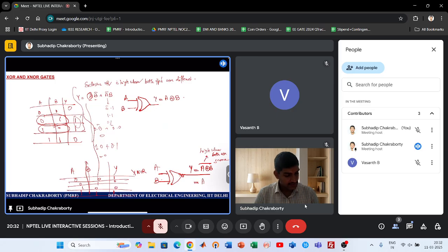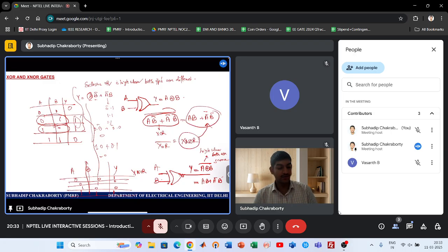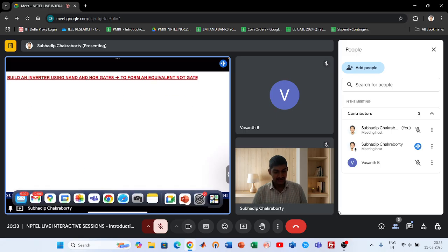And it is actually A B plus A bar B bar. So I will make you prove also that A B bar plus A bar B, if you take the complement, it will eventually come out to be A B plus A bar B bar, because this part is XOR, and the complement of XOR is what you are getting as XNOR, which is nothing but this one. So the complement of XOR is XNOR. That expression I will make you derive using De Morgan's theorem. So we'll actually do this exercise, but before that I have a small exercise for you.